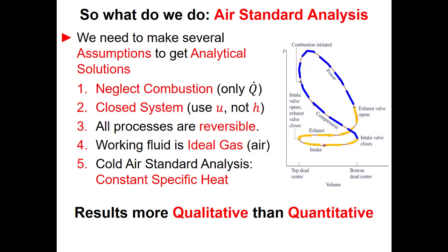We'll assume that all the processes are reversible, meaning that they're not generating entropy. We'll also assume that the working fluid is an ideal gas or air, even though this is not true because in real life there's an air-fuel mixture that's changing over time as we're burning the fuel. And we'll also sometimes make the further assumption that the air has a constant specific heat. Sometimes we call that a cold air standard analysis.